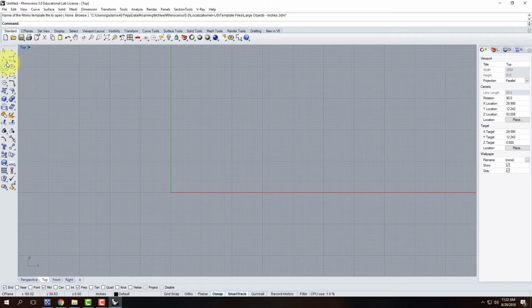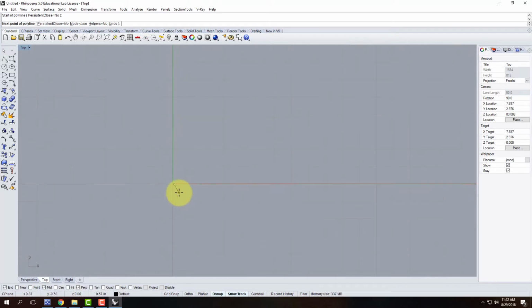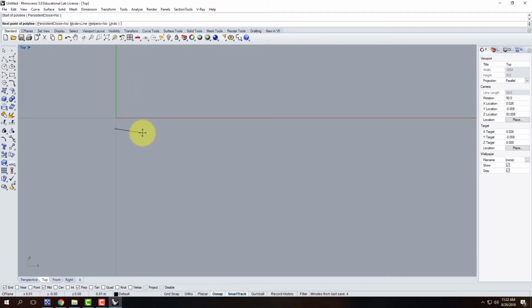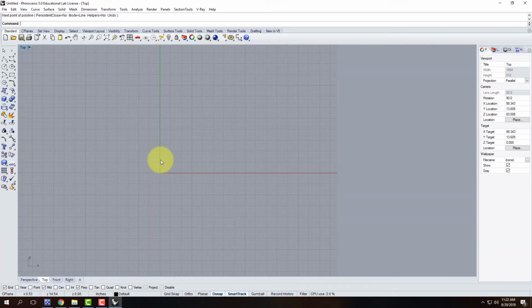And so if I were to start to draw, and let's say that I chose a polyline, for example, and I were to say, I'm going to put it right on that point. Now, as I start to zoom in, you can see that, well, wait, it's not quite where the two points meet. It's not really there. So, okay, well, this time I'll be really good, and I'll make sure I line up right over the top of it. There it is. Well, the next time I zoom in, nope, it's still not there. So instead of manually trying to pick where the origin is, we're actually going to use these coordinates, these x and y values, to determine where we're starting to draw.